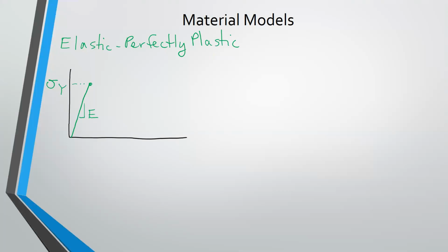So you have a horizontal plateau here. That means once it reaches a point that it can carry a certain amount of stress, it just deforms somewhat continuously. You have what we call a plastic hinge. So that material is now moving freely due to that force, and there's no additional stress capacity.